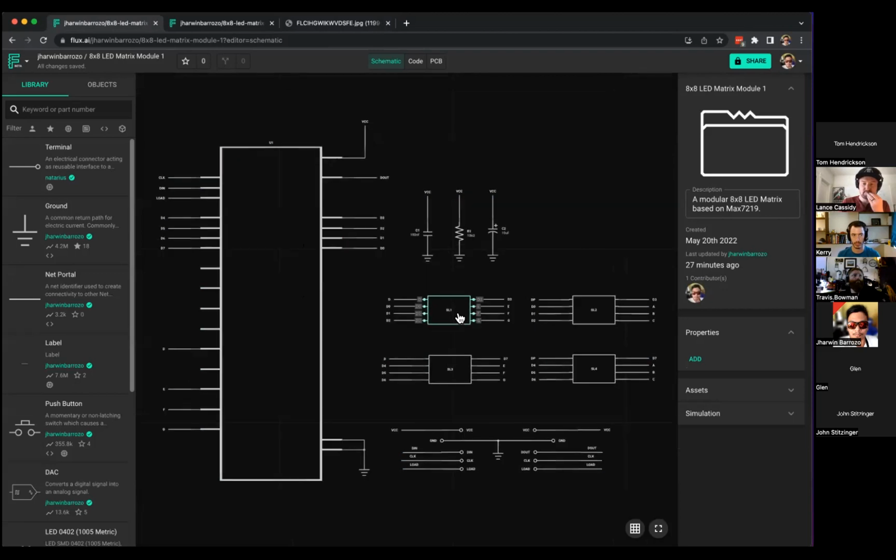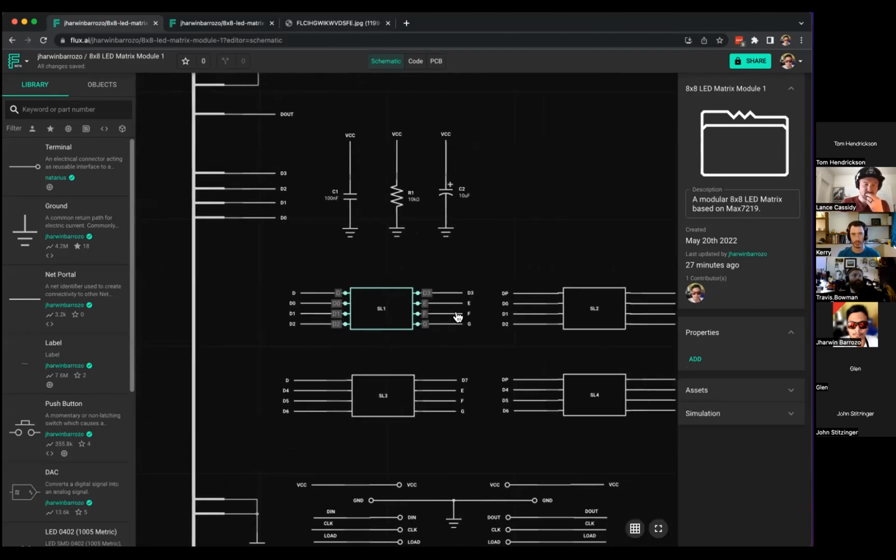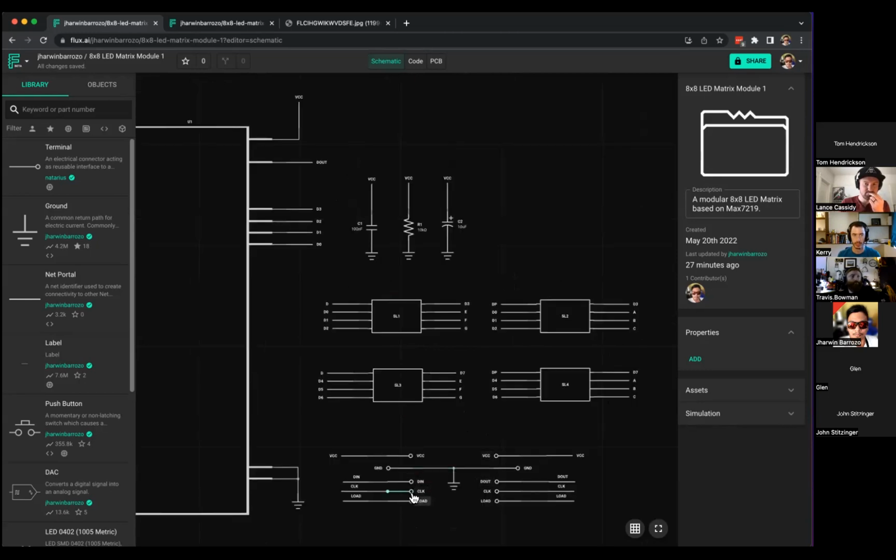And this one here, you see this SL1, 2, 3, 4. These are the sub layouts that we have created in the last session. If you remember the termination point, yeah, they are here. And also these terminals here are the termination points later on where you connect this pad when you daisy chain. Okay, so we'll just focus on the PCB side.